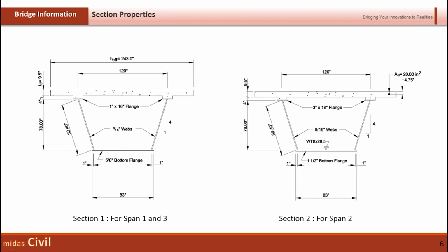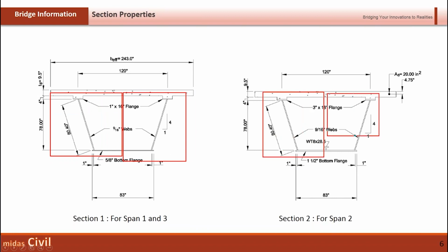So these are the section properties that we'll be considering in our model. Usually, as you guys are already aware, if you are going to do a steel tub bridge, you will consider this I section separately, this I section separately, and all these things separately. It leads to some design issues if you model in such a way, because it doesn't take the Saint Venant torsion properly.